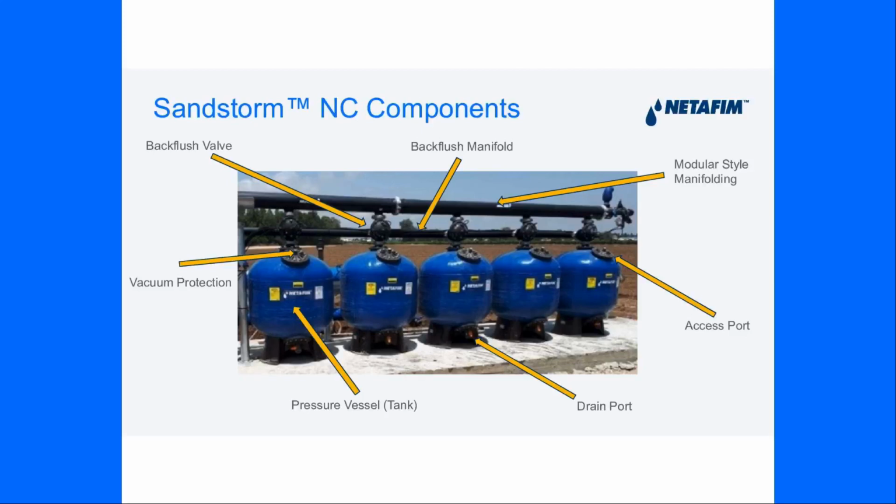In addition to what I've mentioned, you'll also see that in each one of the tanks, there is also a little vacuum protection device. So not only is it super important with these tanks to get the air out of the system at startup, it's probably more important to let air into the system as it shuts down, so that we don't have any vacuum damage, basically having the tanks collapse. So that was also worked into the design.